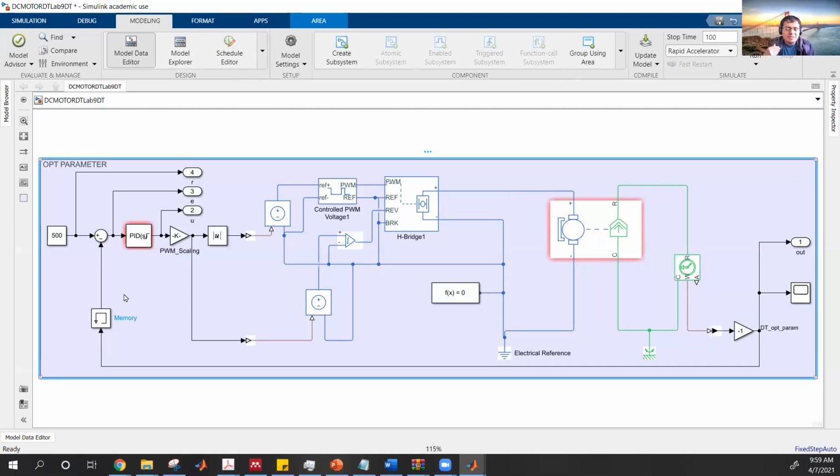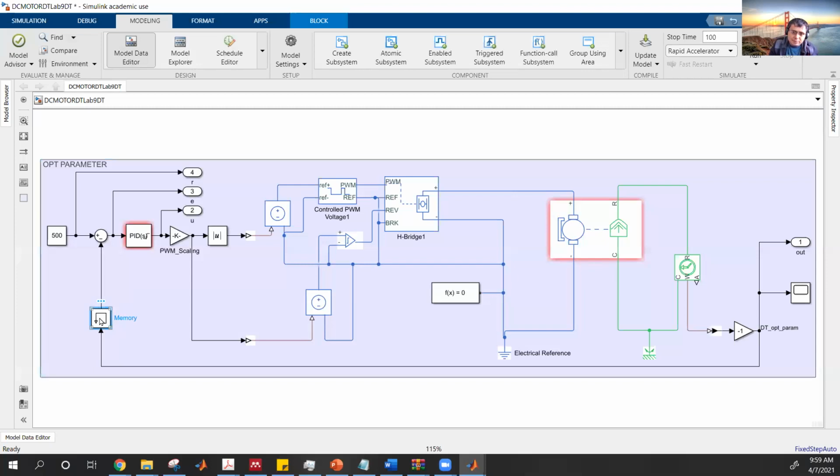However, because we want to perform this in the web application, the solver for the web app is not able to assume those initial conditions. So that produces an algebraic loop. In a regular Simulink execution, we don't have any such problems. But when we want to make web deployment, we will have that issue.